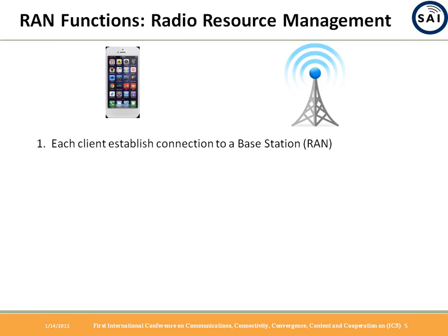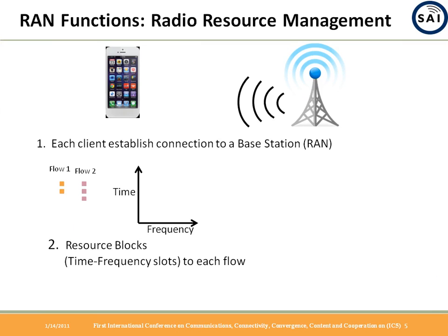Specifically, what are the RAN core functions? First, the RAN needs to establish connectivity. The base station needs to establish connectivity with the cell phone. In this process we analyze the signal strengths, RSSI and CINR values, based on the mode of implementation, either FDD or TDD, time division mode. The demonstrations will all be shown in FDD mode, frequency division duplex, which has been implemented by Verizon and AT&T and so on.